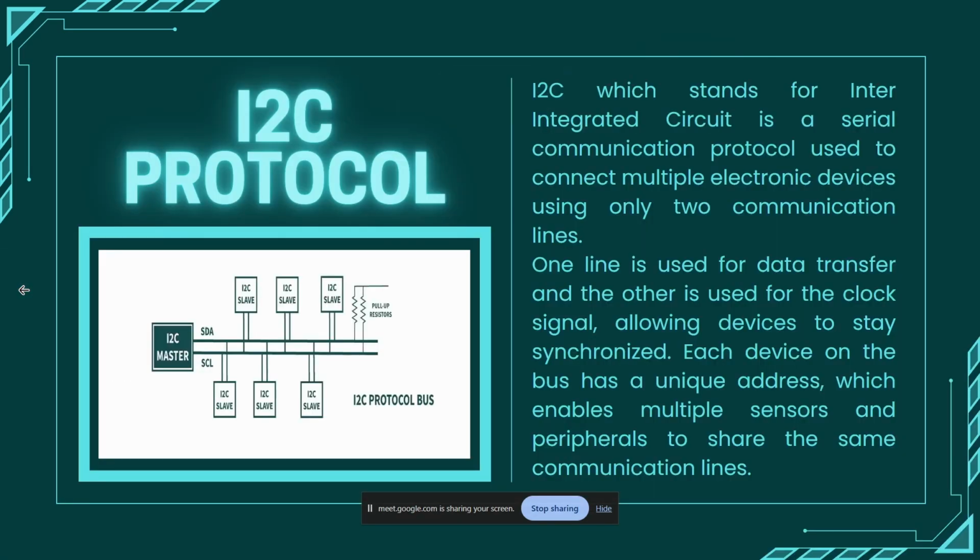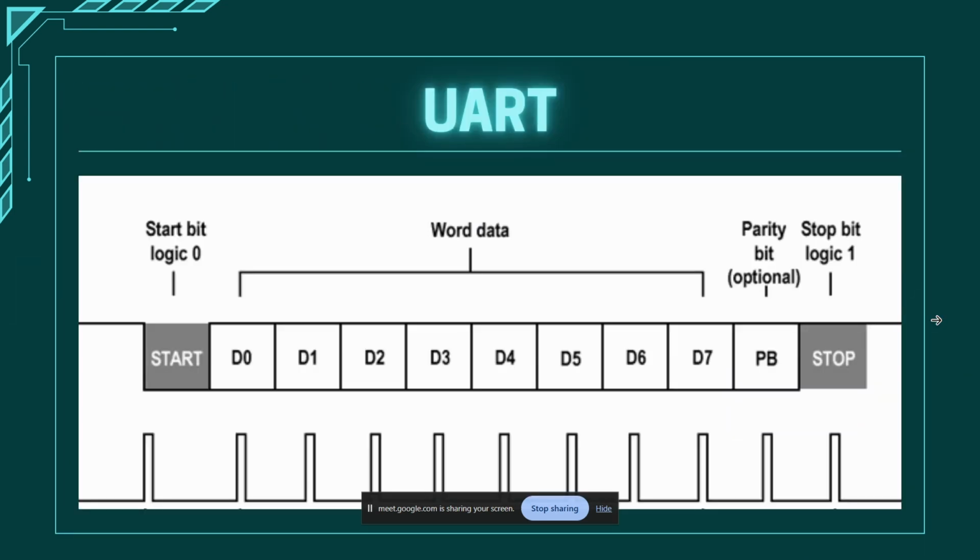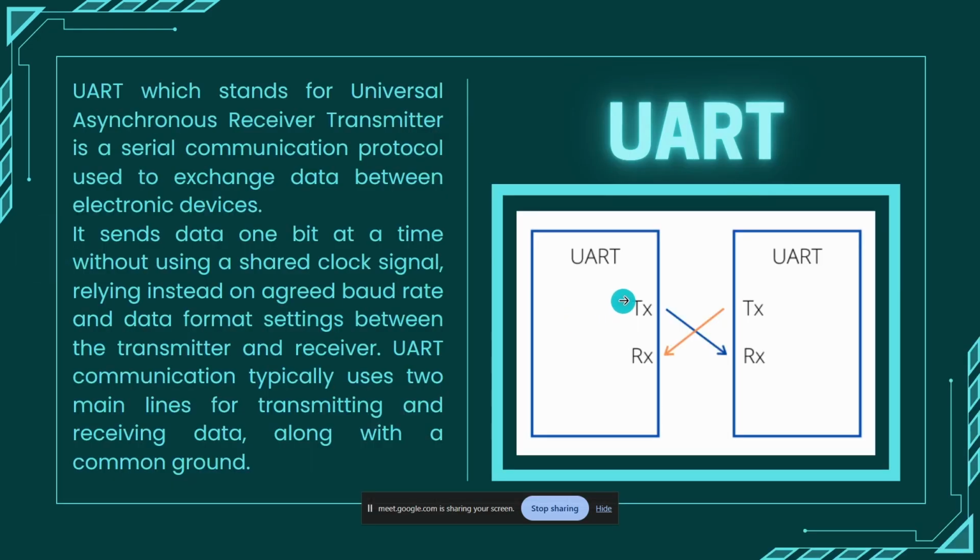So we have something called duplex. Duplex just means a two-way road, like we have a two-way communication. So in UART, usually your first transmission goes to the second guy's receiver, and the second guy's transmission goes to the first guy's receiver. So the entire thing is a duplex form of communication. We have a two-lane highway where data can go from one side to the other, and the other side to the first. Okay, you have data flow from first unit to second unit and second unit to first unit.